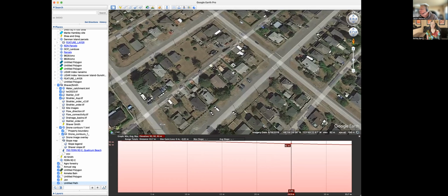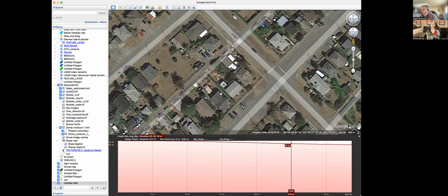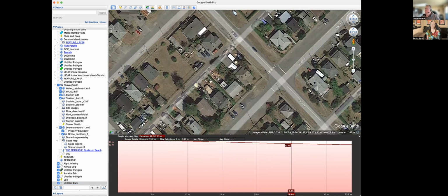And what we can do here is we'd want to indicate on our base plan where this line has been placed, and have an A and a B on each end. It doesn't matter which end has A and which end has B. And then we are going to make sure that when we do our cross-section drawing, that we put A on one side and B on the other. And that's just so we know which side of this line we're viewing from. And so this is how we would get that elevation snapshot.